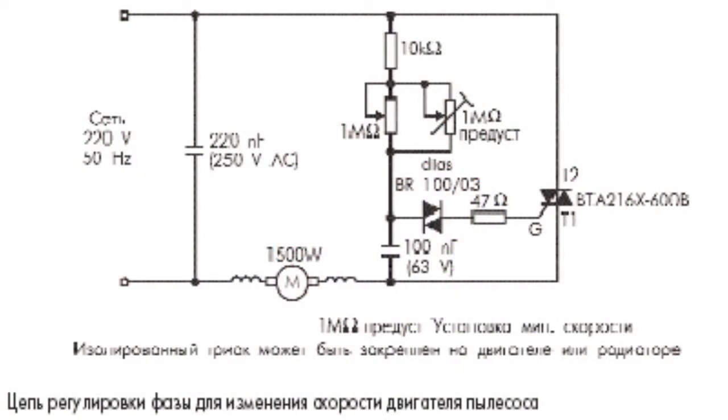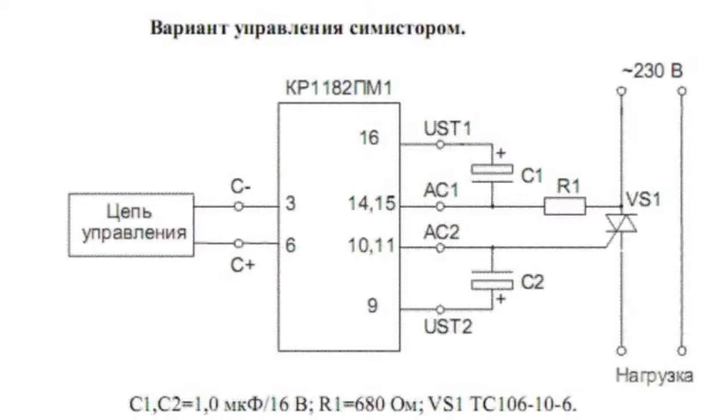Most devices work in quadrants 1 plus and 3 minus phase control, or in quadrants 1 minus and 3 minus unipolar control with the help of integrated circuits and other electronic circuits. Thus, the inability to carry out control function in quadrant 3 plus is a small price to pay for all the above mentioned advantages.